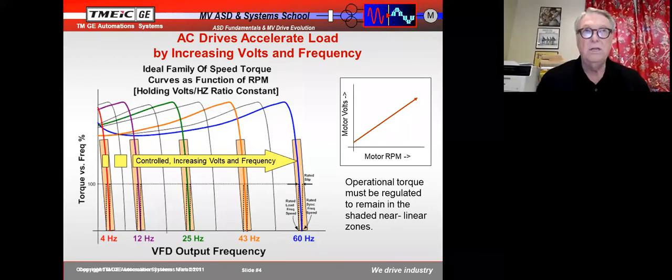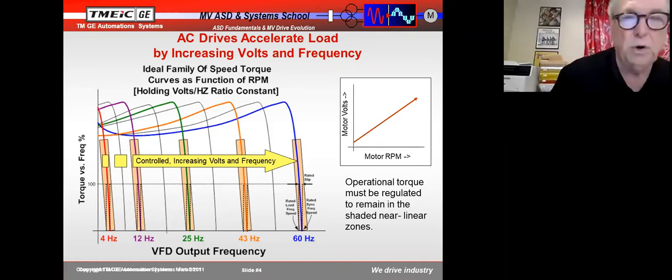And so it only knows the difference between its speed and that 1800 RPM going around the stator. So in an adjustable frequency drive, we never get into the starting portions of that motor curve, only the running portions. And we start out way down here on this red curve. Let's say we're running at 4 hertz. We're not starting at 4 hertz, we're already running at 4 hertz. Therefore, guess what? Your current is proportional to the torque, and you get 50% current at 50% torque.